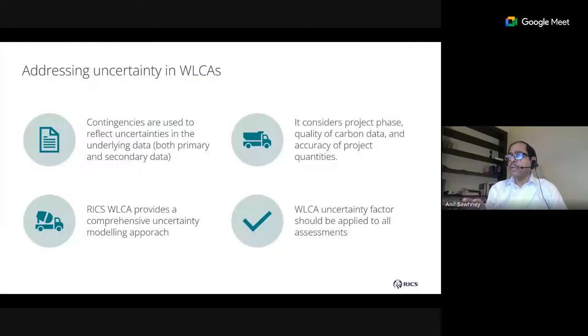When we picked up an EPD for concrete in EC3, it provided an uplift factor. In some places it was 9%, we saw some EPDs with 11%, and I think there was one with even 20%. So if the EPD gives a certain GWP value, you are then asked to further uplift it, multiplied by 1.1 or 1.095 as we saw.